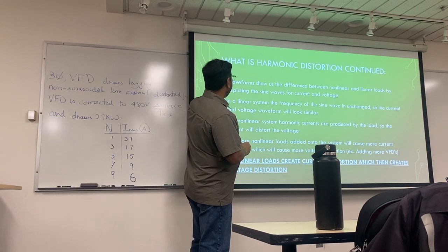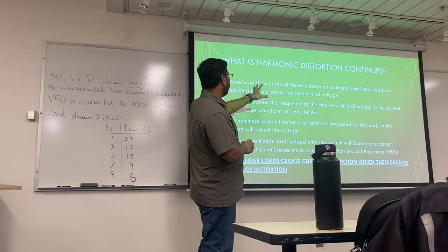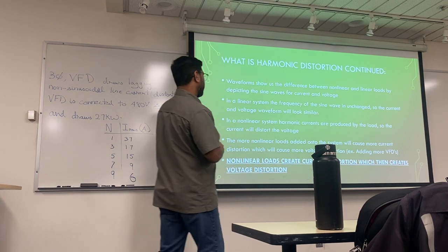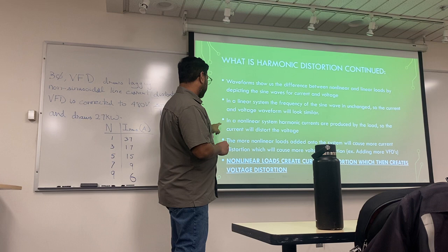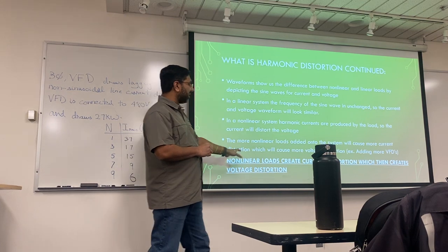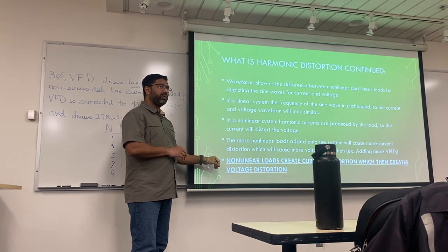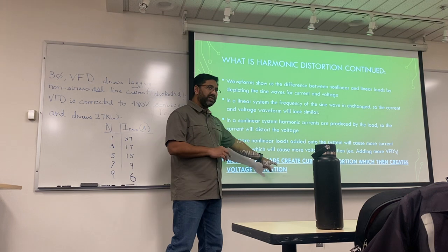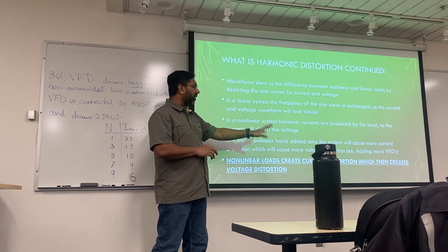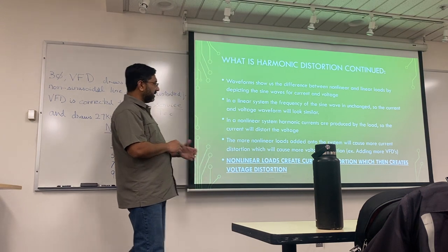Again, the waveform shows the difference between linear and non-linear. If you look at the current, it should immediately pop out to you whether it's linear or non-linear. With a linear load, current and voltage look similar. I just wanted to put it once more that non-linear loads create a current distortion, which then creates a voltage distortion. What I'm trying to say, from a utility's perspective, is that we don't create a voltage distortion. We want you to have a sine wave, but what you put on as a load is your business, and that can create a current distortion and thereby affect our voltages.